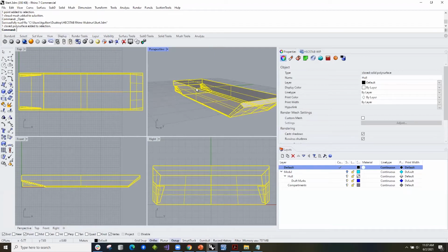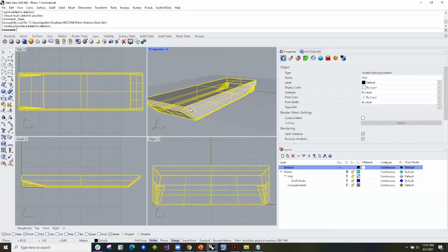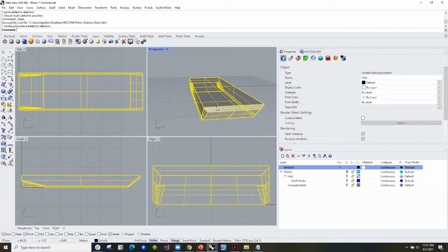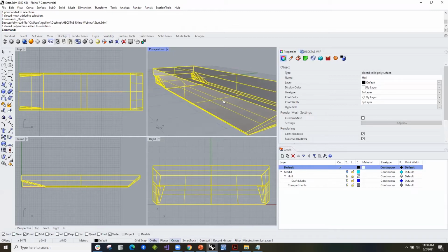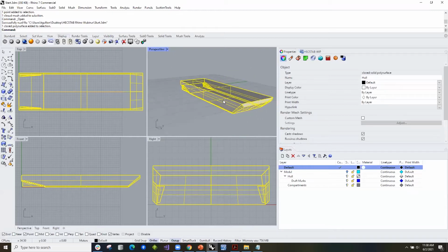That's a whole other discussion in Rhino, and not one I'm an expert in, so I wouldn't give that talk. But I think the biggest challenge in using Rhino will be that at some layer you've got to develop the base hull model, because from the base hull model will flow all the compartmentation. And the higher quality your hull model is, the higher quality the entire model is. So it's worth spending the time on it.